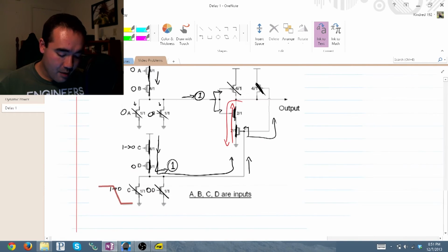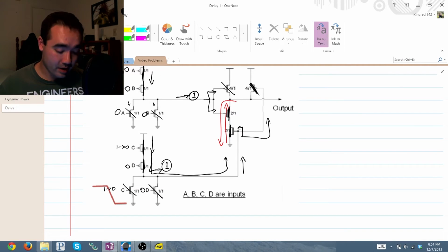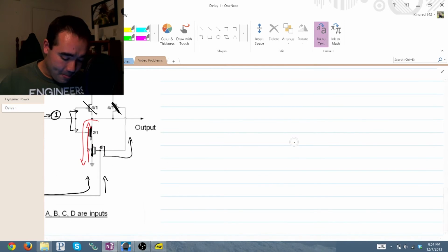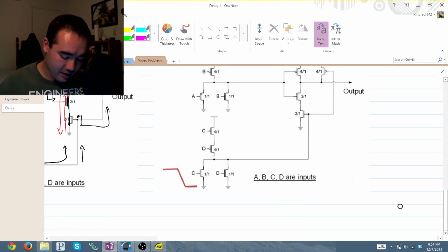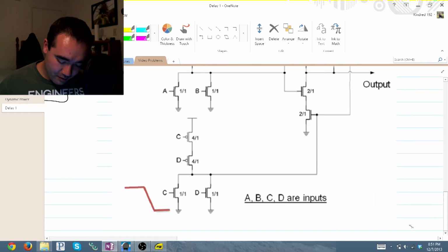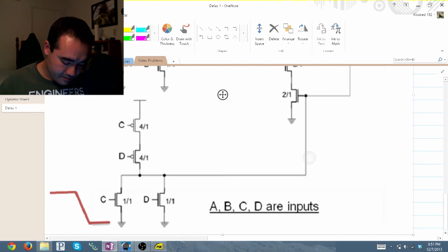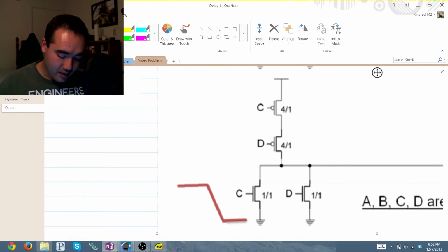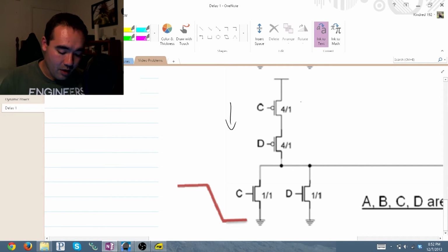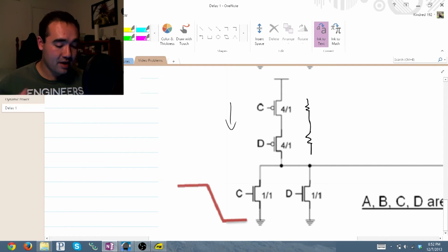And that's really it. Now we're going to get to the point where we're going to start drawing our equivalent resistances and capacitances. And here's a trick that will help you determine how you're going to assign things. Let's go ahead and blow this guy up so we make it easier for us to write. Alright, starting again at the input stage. Now, you know that our path of propagation will be this way. Therefore, our resistances will be through those transistors. It makes sense, our current's traveling through there. Those are the equivalent resistances that you're going to consider when you're calculating your Elmore delay.